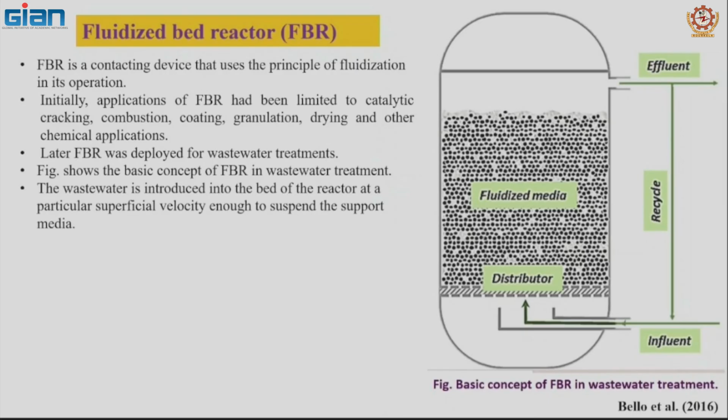The wastewater is introduced into the bed of the reactor at a particular superficial velocity. Superficial velocity is nothing but the empty column velocity of the fluid that is flowing through the vessel, as if there were no solids. So what would be the velocity of the fluid if it flows through the vessel only? That is nothing but the superficial velocity. So at a particular superficial velocity, enough to suspend the supported media.